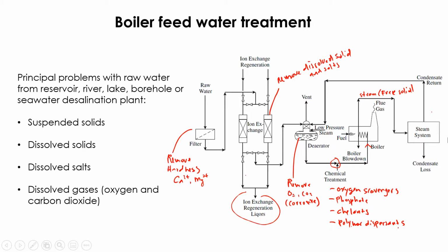The next question is how much we can return. Typically, it's less than 90%. Why? Of course, we can return the condensate as high as possible, but the problem is the investment cost. Maybe in one condensate stream, the flow rate is too small, and then it is not attractive economically to pipe back the condensate to the return condensate stream.